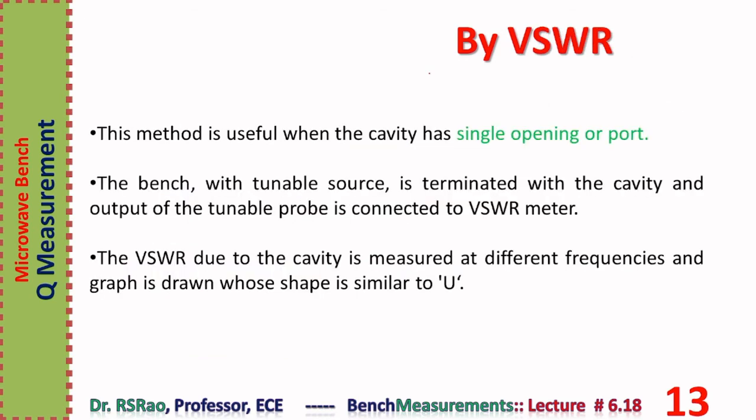There is another method. This method is suitable when the cavity has a single opening. It is by measuring VSWR. This method measures Q of the cavity by measuring VSWR at different frequencies.